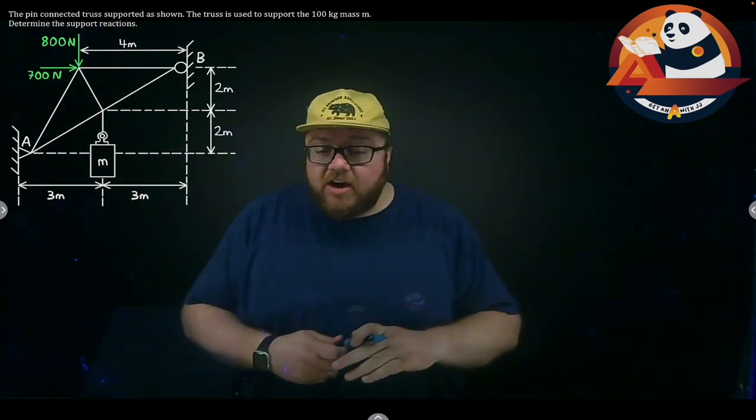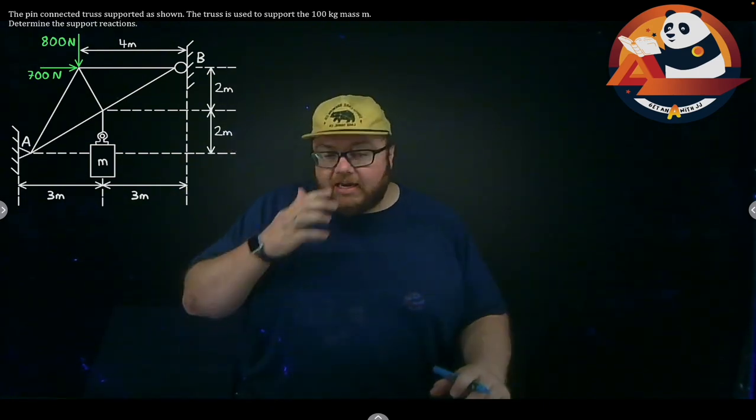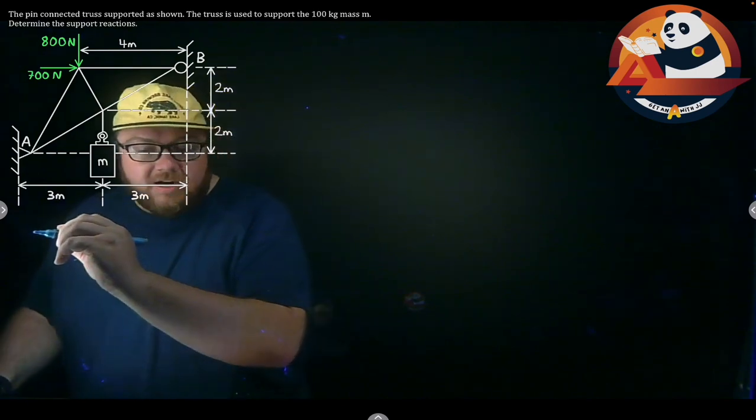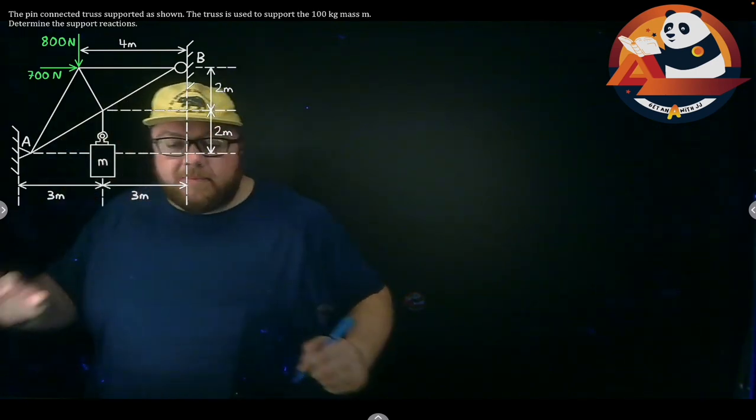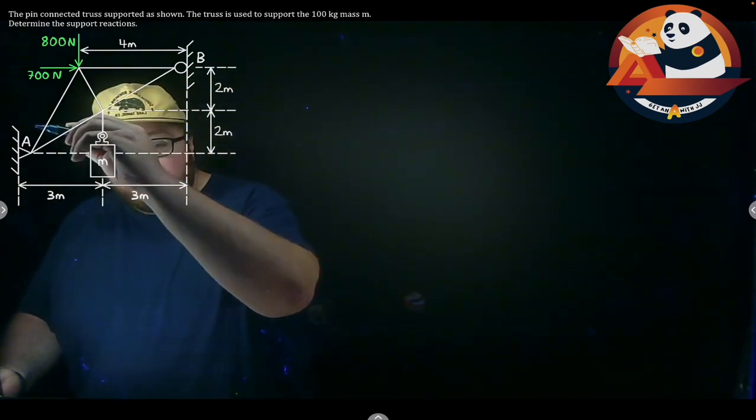So again, we're going to start out and tackle a free body diagram. We have to have a free body diagram for making equilibrium equations, so that should be our first step. For doing that, let's start by circling around our object, cutting it off of the wall that's holding it up, or the ground. Any weight that's hanging off of something, we'll snip that rope as well and go from there.